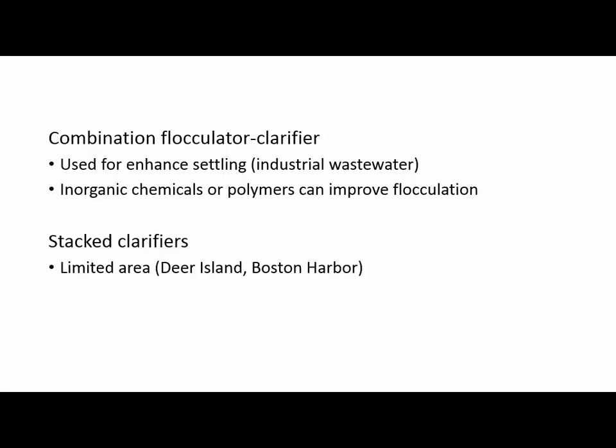Industrial wastewater needs more time to settle the suspended solids and others. And also, if you add an inorganic chemical or polymer, it can improve the flocculation, which can enhance the settling.